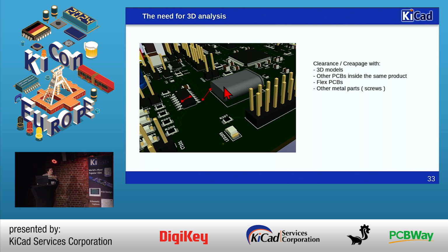This one also is tricky because the pads are here, but there could be an arc here, and there's no copper feature for this component here. So this is basically why we need a 3D check if we want something that is really, really safe, or if we want to be maybe more compact than we can be without having problems with clearance and creepage.